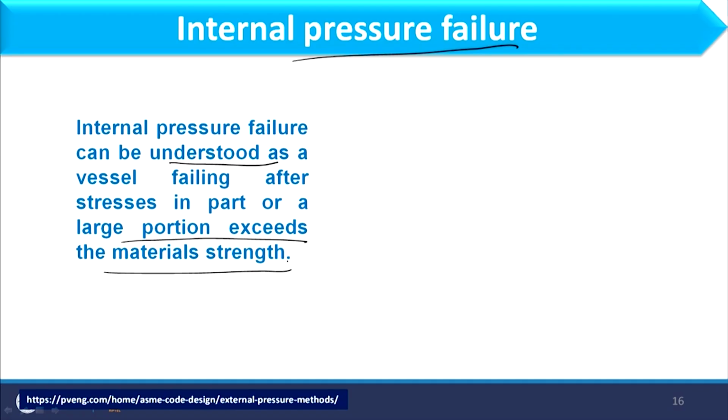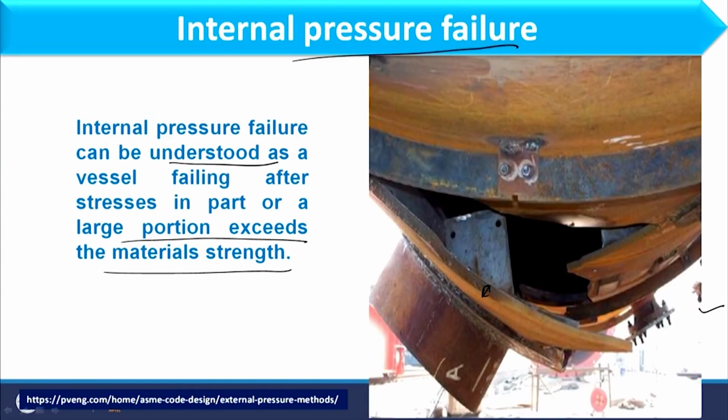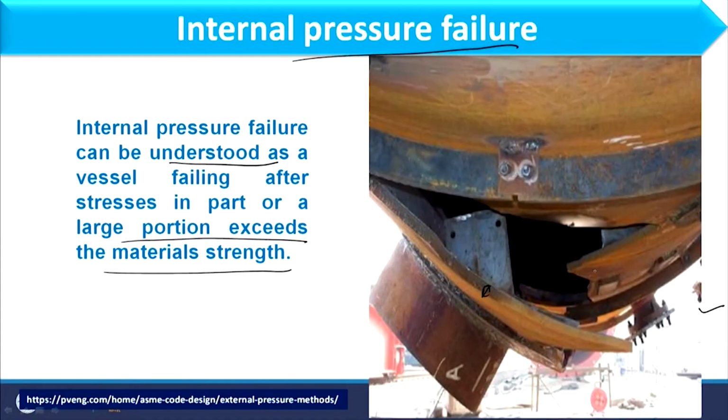So, as far as internal pressure failure is considered, in that case bursting of the vessel will occur, as we have shown in this image. You can imagine that thickness is so much, but still failure will occur because stress will exceed the strength of the material, and that can be defined as damaging stress of the material. Now, till now we have derived the expression for thickness of cylindrical as well as spherical pressure vessel, and considering